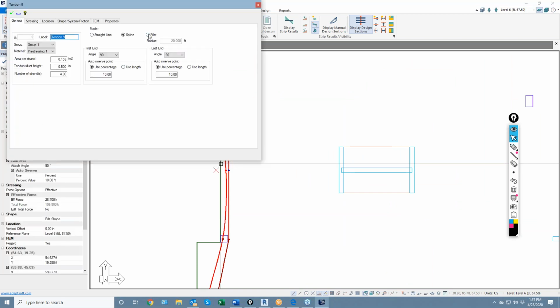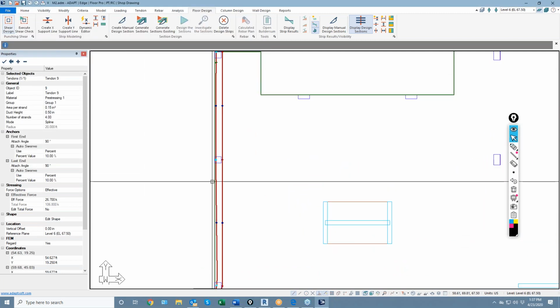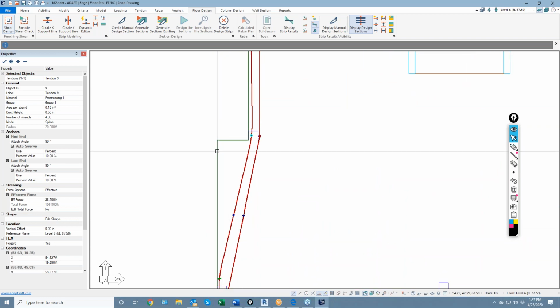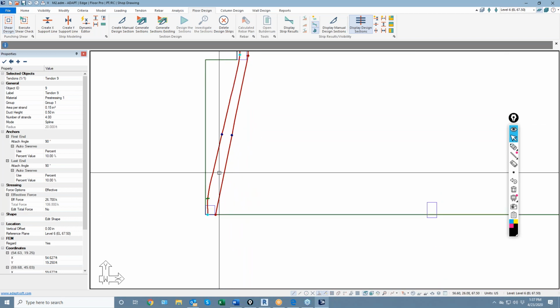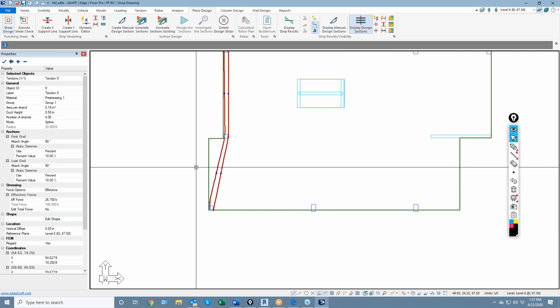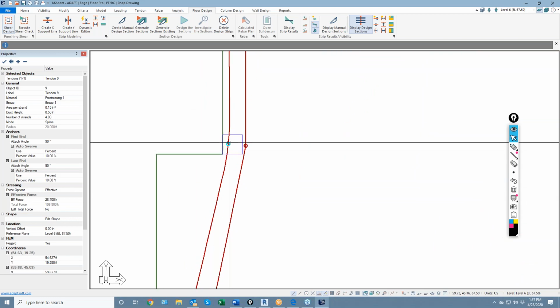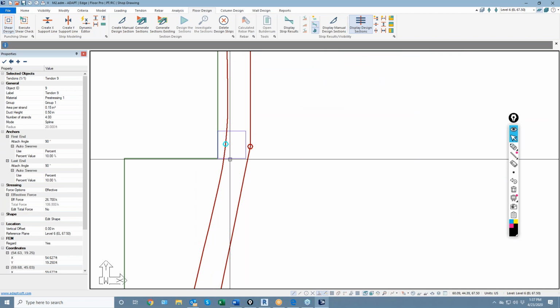So another option would be to use the fillet with a radius, and that option allows you to keep these tendons essentially linearized, and then where it turns, you have some radius here where that point is right there, and then on the opposite side right here. So this is kind of an in-between linear and spline, and both the fillet and the spline options will produce a separate color for the high point. You can see this is like magenta versus red.